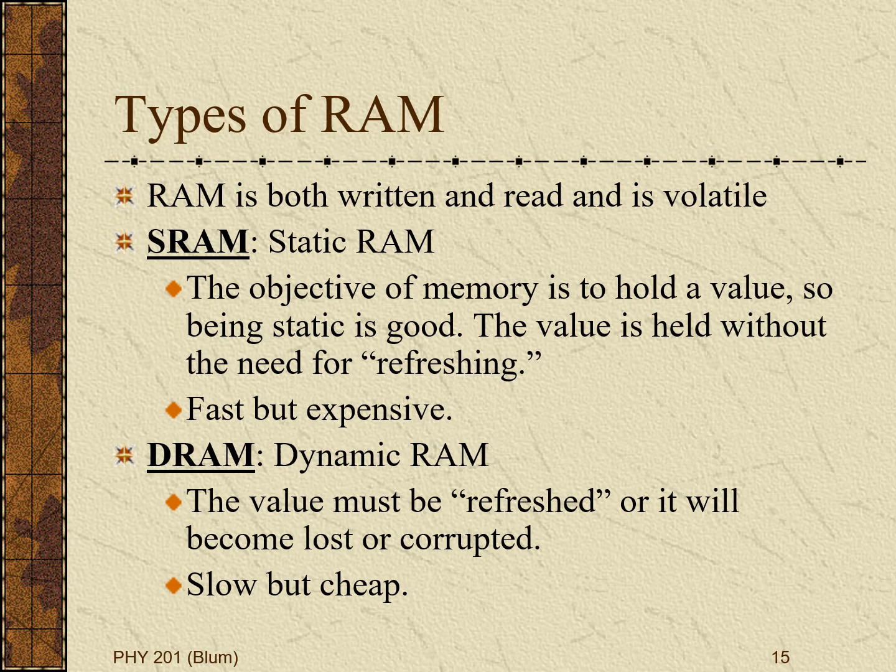Within RAM, we have two main types, SRAM and DRAM, static RAM and dynamic RAM. And don't go by the normal feeling that you have for these adjectives. Remember that in memory, the purpose is to hold on to a state, to remember some history. And so in that case, static is good and dynamic is bad.